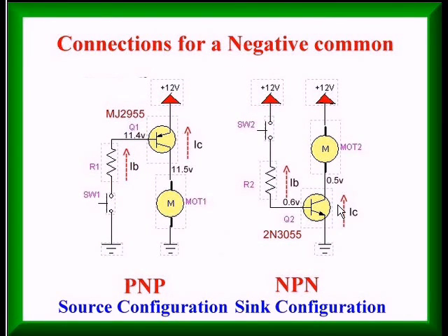All right, looking here. If you're using a negative ground, which you're stuck with on Arduino, PIC or any other modern microcontroller, they use a negative ground and a positive VCC. So you will have to connect the commons of the two together. But because of the output being plus 5 volts or plus 3 volts, you have to handle the transistor drivers differently.